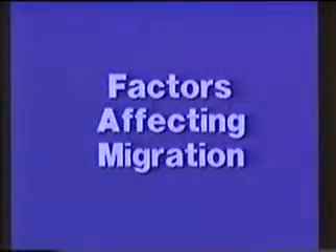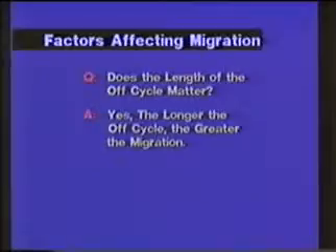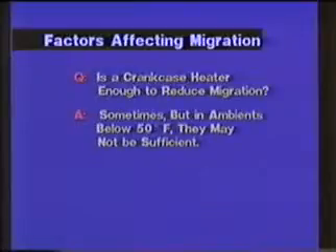Let's look at some of the factors that affect migration. First, how long is the compressor off? The longer it is off, the more time is available for migration to take place. Compressors that run continuously or are not off long enough for the oil to become too cool generally do not have migration problems. Secondly, what is the coldest ambient temperature the compressor is exposed to?